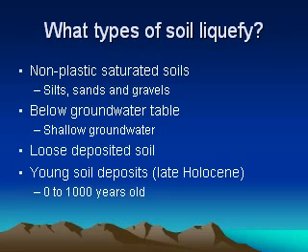First of all, what types of soils liquefy? Well, typically non-plastic saturated soils such as silt, sands, and gravels that are located below the groundwater table tend to liquefy. You don't have to have a groundwater table; you could have perched water, but basically it's due to shallow groundwater. Also, loosely deposited soils, soils that geologically were deposited, like colluvial, alluvial, or fluvial deposits that aren't in a dense condition, also have a high potential for liquefaction.